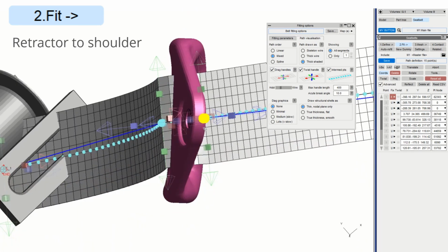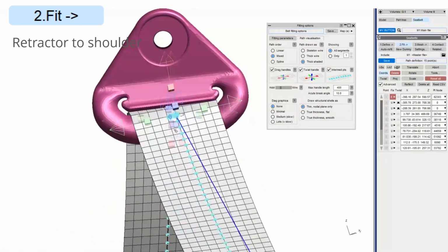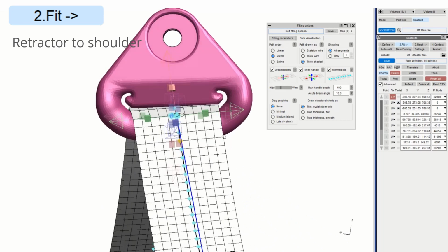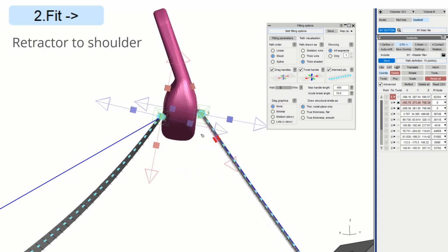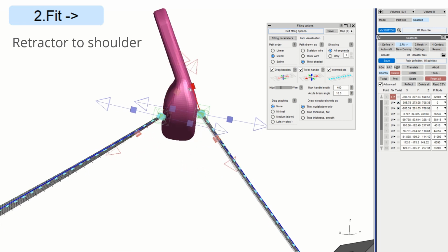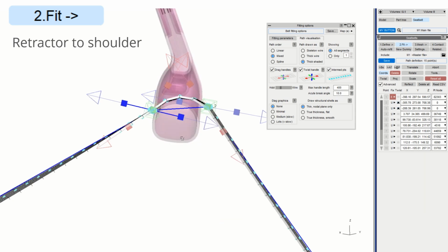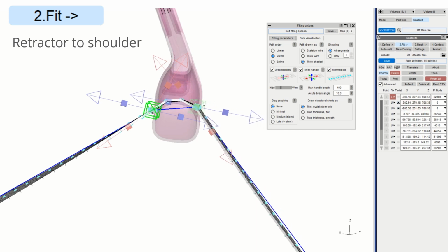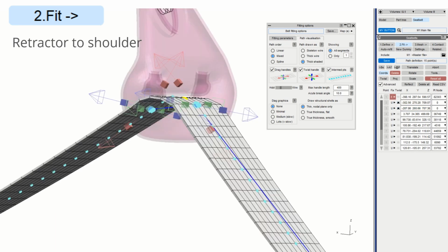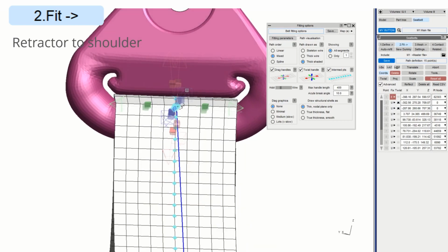and just modifying the points there. Then the green ones to align the belt plane with the structure as we did before. I'm now right clicking on the green drag handles, nearly finished. We can then use the red ones to control the belt angle coming into the slip ring and through the slip ring. Using transparency and looking down the line of the slip ring can help us visualize, get that in the slot. It's not very difficult, trust me, after a bit of practice. That's looking good.